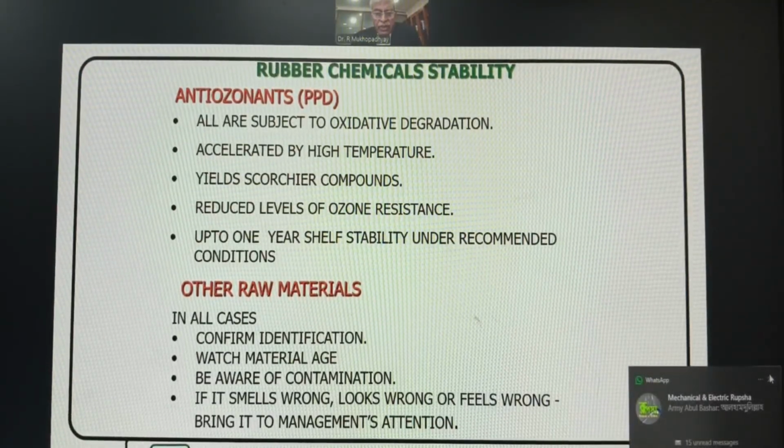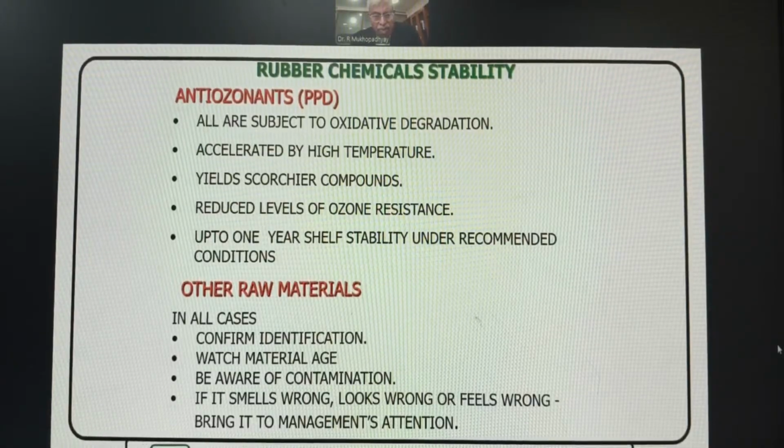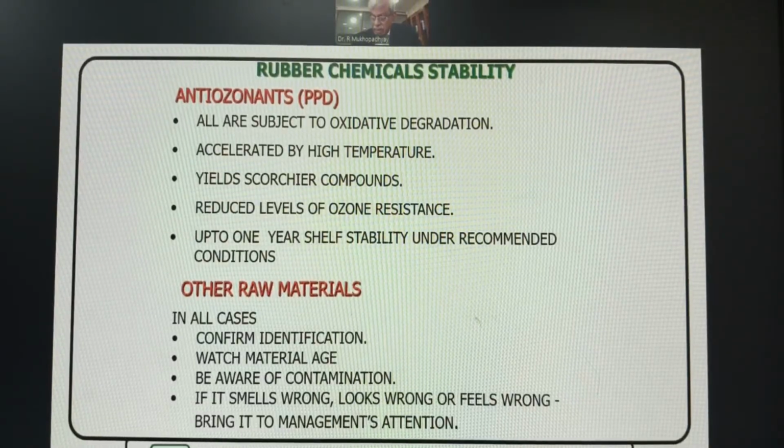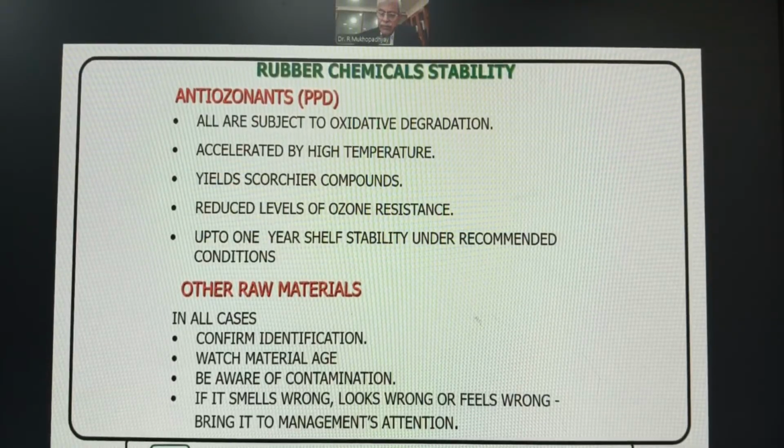Other raw materials: generally all the materials should be identified and stored properly, and acidic and basic materials should not be stayed together. Similarly, saturated and unsaturated rubber should not be placed side by side.